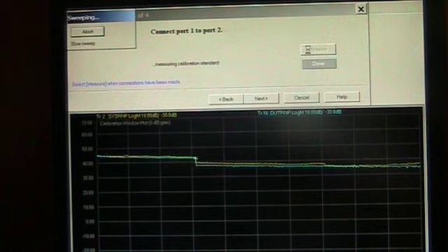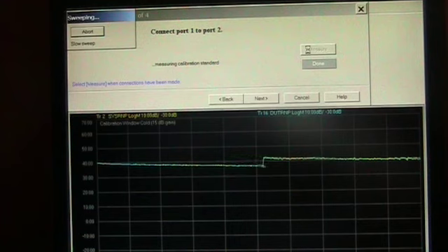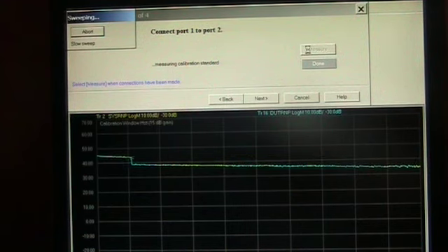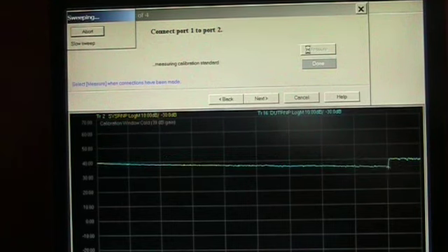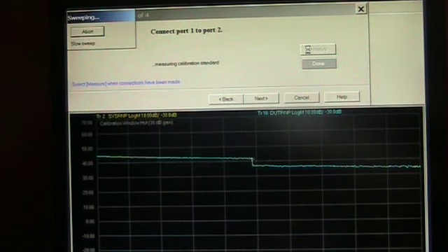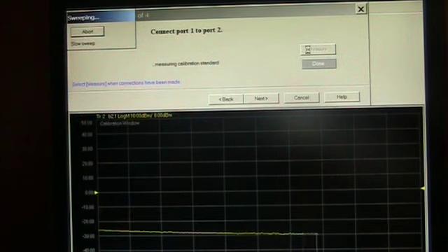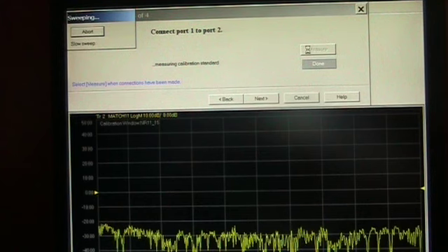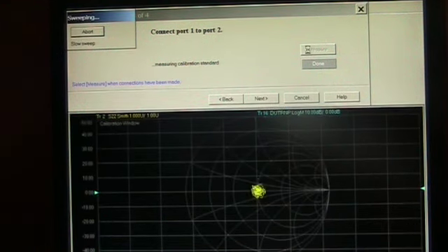Again, there are a number of steps that are performed for all 3 of the gain stages with the network analyzer. This step takes approximately 1 minute, and in the case of the measurements that are performed in this setup today, the frequency steps are from 2 to 50 gigahertz in 100 megahertz steps, and so that's a little bit higher resolution than what's required for noise parameter measurements, but it's performed here today so we can demonstrate part of what we're seeing in the raw noise figure measurements under source pull.